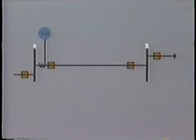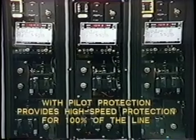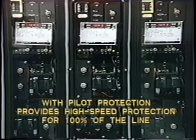With instantaneous overcurrent relays, we have another problem. Due to their lack of high precision, the instantaneous relay is set to cover only 80% of the line. This is necessary to prevent the relay overreaching into the next section of line. Pilot relaying helps us achieve high-speed protection on 100% of the line. There are several different methods of applying pilot protection, as we'll see.